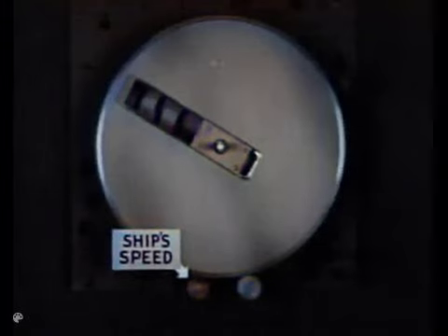The pin extends up through the slot in the vector gear so that pin and follower can move only along the slot. Ship speed is entered through this input gear. With a transparent vector gear, you can see how the spiral groove moves the follower and pin along the slot.